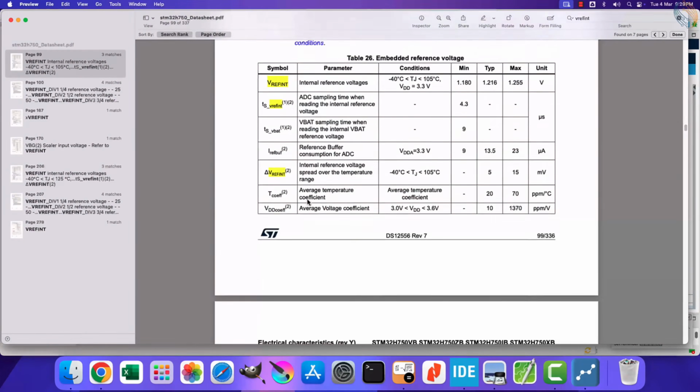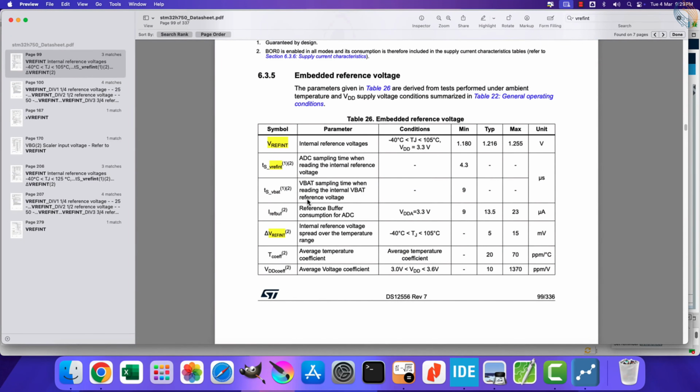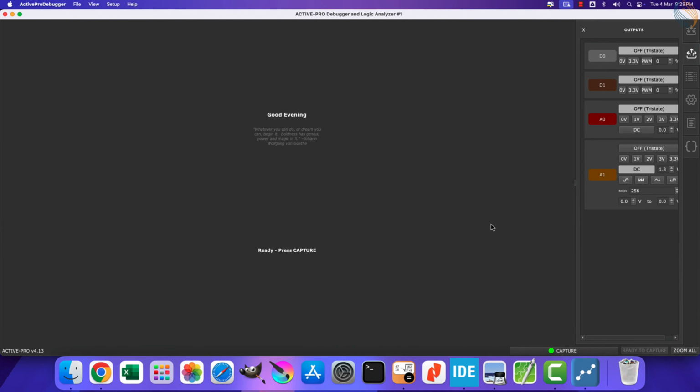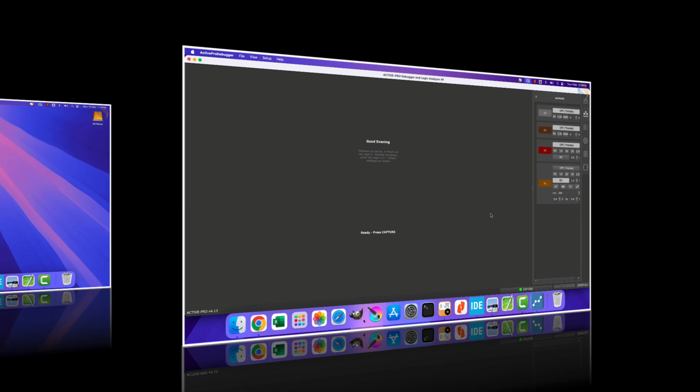So you saw how we can use the external reference voltage to reduce the reference point for the ADC input voltage. This can help us get the maximum resolution, even at the low voltages. Also for the devices, where a separate Vref pin is not available, we can reduce the VDD itself.